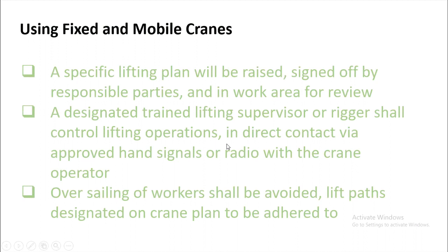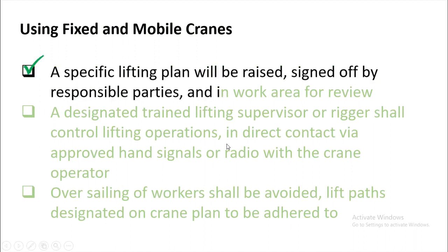Using fixed and mobile cranes, a specific lifting plan will be raised, signed off by responsible parties, and kept in the work area for review. So if you are using fixed or mobile cranes, they should have a specific lifting plan. And make sure that the lifting plan is signed by responsible persons, and that it is available in the area for review by authorities or any concerned persons.